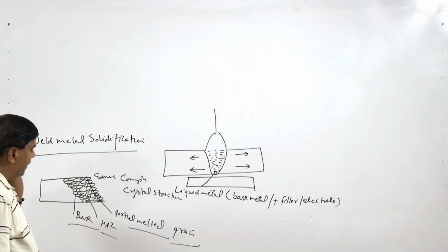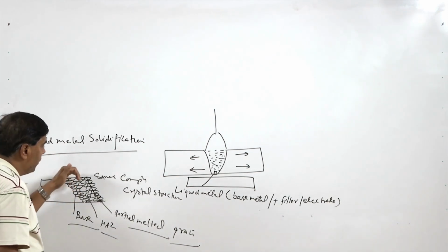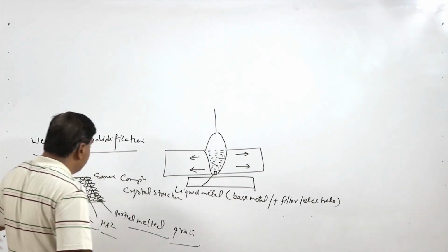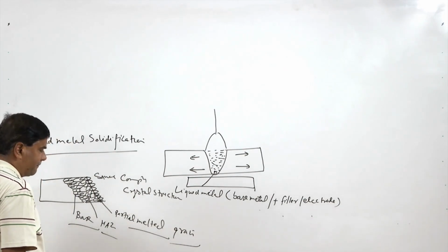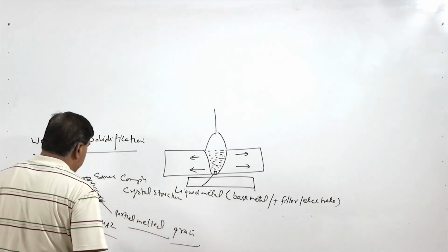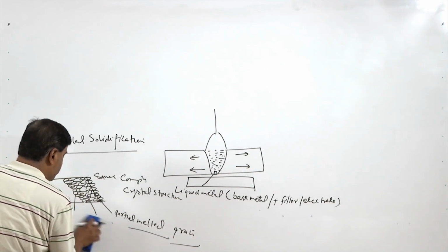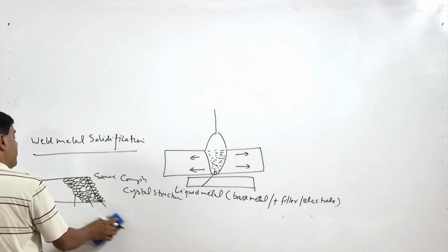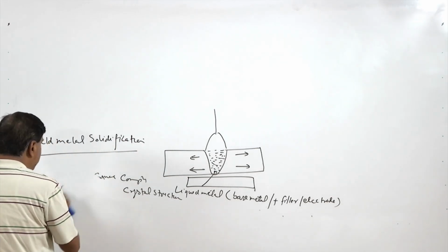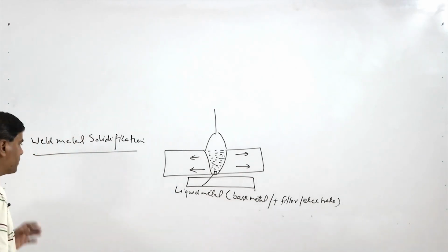primarily takes place in the course of the solidification, when the composition of the filler and the base metal is the same, and the crystal structure of the base and the filler or of the weld metal which will be produced are the same. So, in that case we will have just the growth mechanism involved in solidification of the base metal, but there is a continuous change also in the grain structure which is observed.